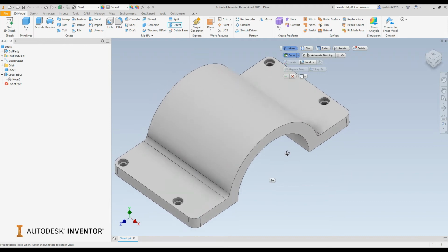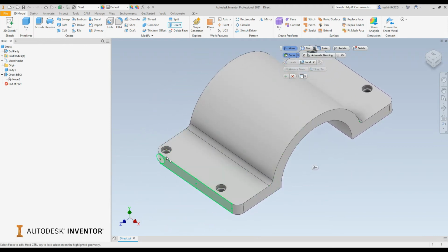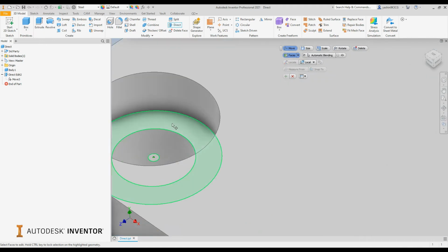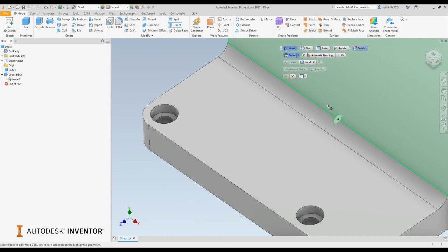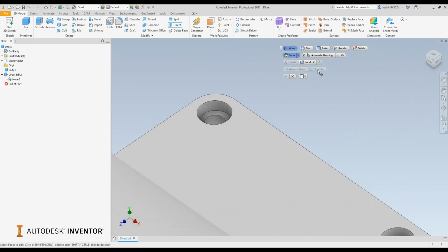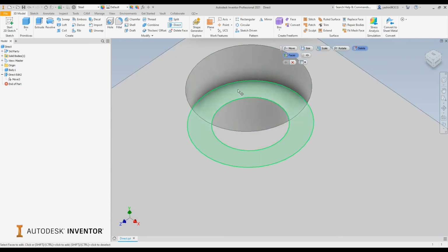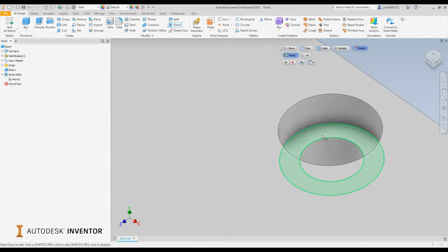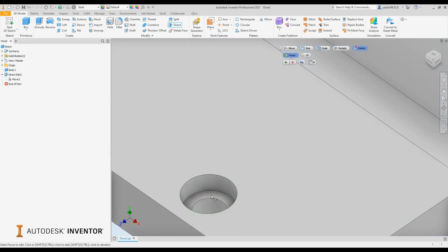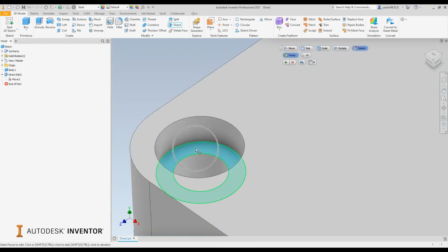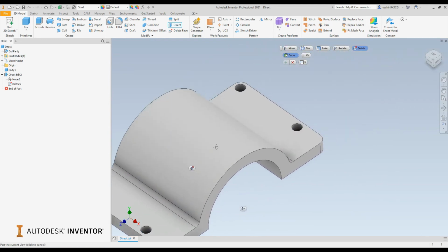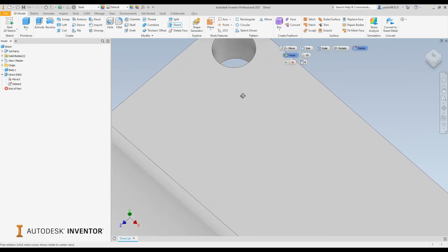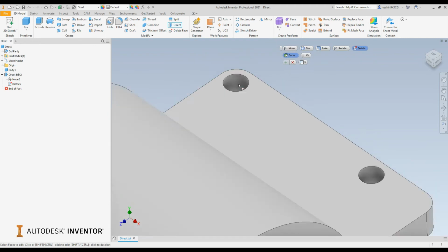And you'll see that increases the overall length of the part itself. Next up, I'd like to change the counterbores. Actually, transform them from counterbore holes to normal holes. How I do this is by using the Delete function in the dialog box. This allows me to delete faces. So all I have to do is simply toggle the Delete function, highlight the faces I'd like to remove, and those would be all the ones on top of the holes themselves that create the counterbores. Once I've grabbed all of those, I simply need to select confirm or apply, and you'll notice those holes have now transformed from counterbore to plain holes.